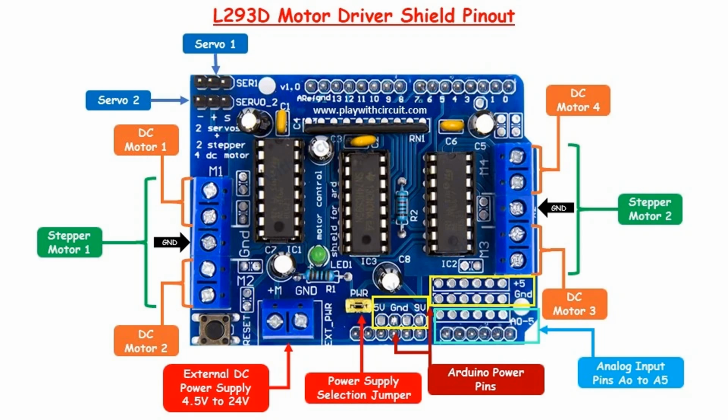4. AC servo motor drivers. Function: AC servo drivers control AC servo motors, which are typically used in industrial applications. These drivers control the motor's speed, torque, and position by regulating the input power. Operation: AC servo drivers often use vector control or field-oriented control (FOC) to precisely control the motor's torque and speed by adjusting the frequency and amplitude of the AC power supplied to the motor.